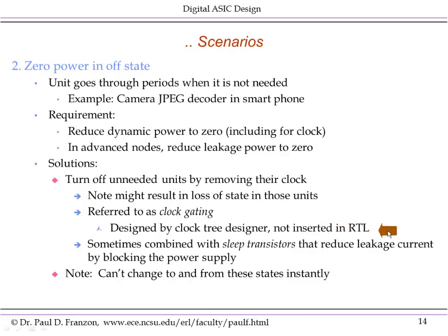And note, and I want to emphasize this, clock gating is done by the clock tree designer, not by the logic designer in the RTL. The system designer says to the clock tree designer, we want a gateable clock so that this JPEG unit can be turned off under system control. Please design the clock tree to enable that. And the clock tree is custom designed.